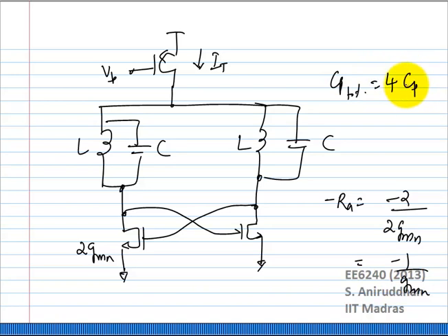So what's the difference? Why would I even go with an NMOS? Why not just take the same original NMOS cross-coupled oscillator and just make the NMOS device size 4 times. So really current reuse is not a real advantage, obviously, right? I have the same parasitic capacitance, same negative resistance. Those are the 2 parameters we have looked at for the oscillator.